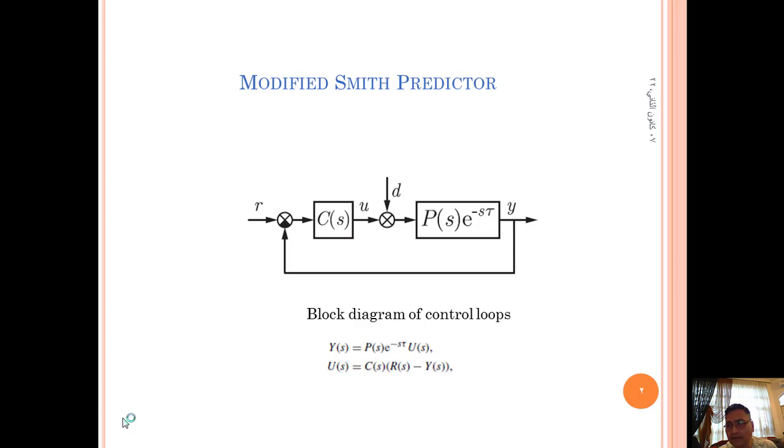An effective way to compensate the destabilizing effect of feedback delays is the application of predictor feedback, such as the Smith predictor or its modification. The main idea of this predictor feedback controller is to estimate the future state of the plant, using the predicted state in the feedback loop instead of the actual one. The effect of time delay can be compensated.